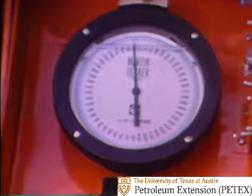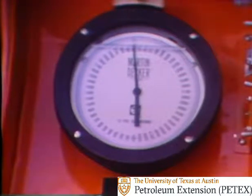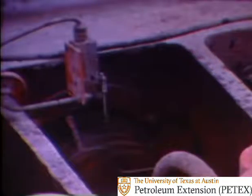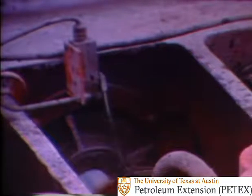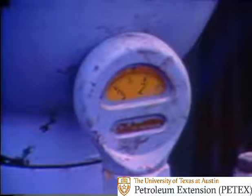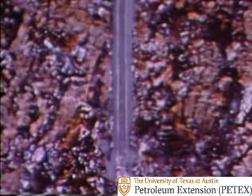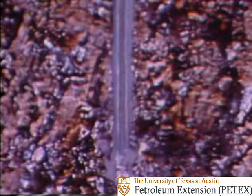Now, let's see how a kick reacts and what pressures are involved when it's circulated out and allowed to expand. Circulating pressure is the pump pressure needed to overcome friction losses in the circulating system. This will include the pressure needed to pump through the drill pipe, drill collars, bit nozzles, and back up the annulus between the wall of the hole and the drill pipe.